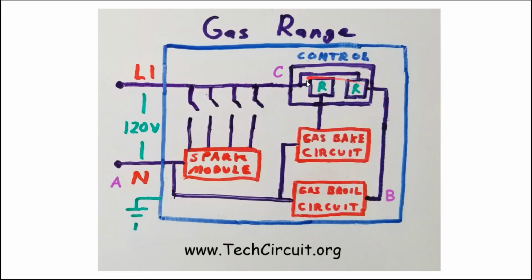So once this control board is replaced, then L1 will make it all the way over here. You're going to have L1 over here, and you're going to have neutral over here. So this is 0 volts, and you're going to have 120 volts.